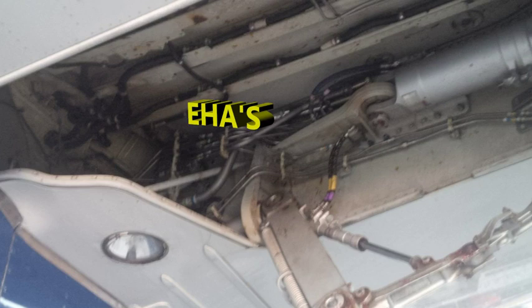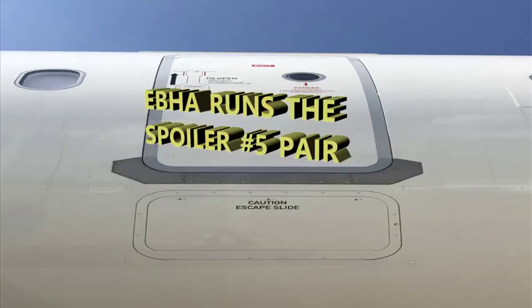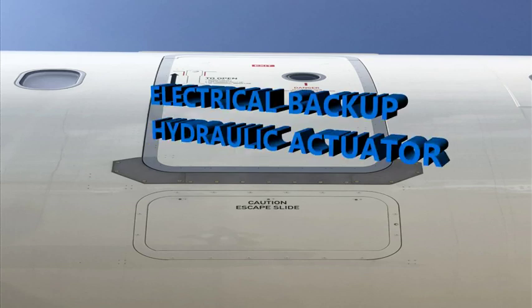All right, remember I mentioned that special pair, spoiler number 5 pair, because that's the only pair of spoilers being run by the electrical backup hydraulic actuator. That's different from the EHA. Just to differentiate, we have an EBHA, which I'm talking about right now, your electrical backup hydraulic actuator that runs only the pair of spoilers number 5, and then you have the electrohydrostatic actuators. The other spoilers are an active motor running off the conventional servo controls.